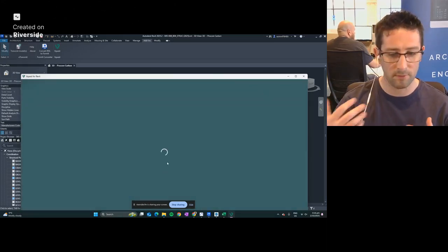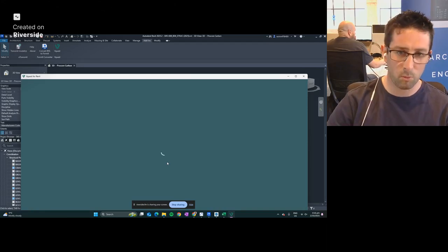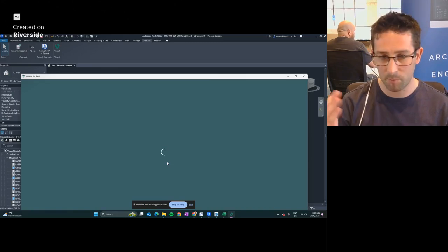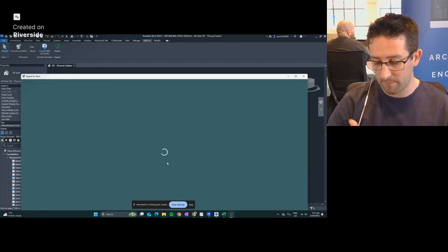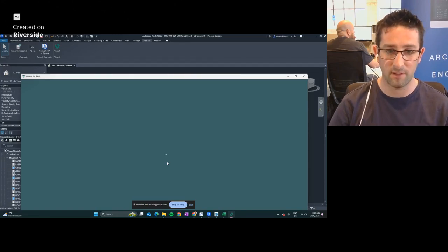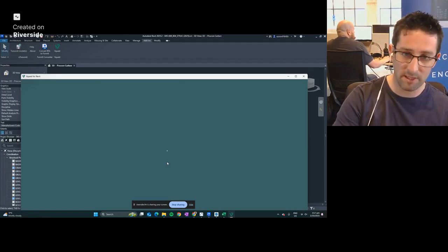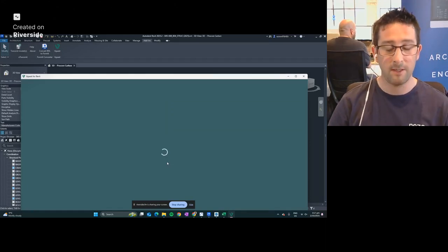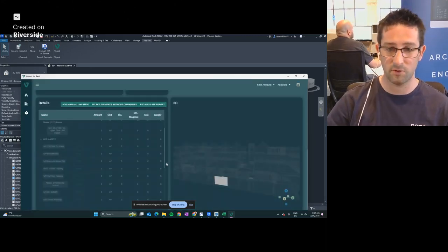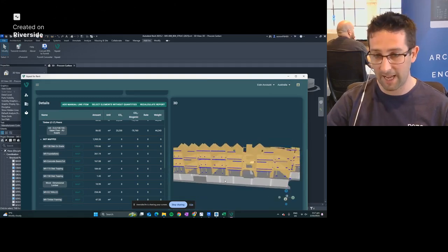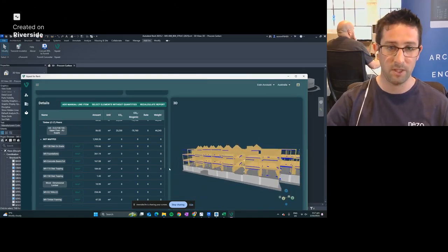So there's a variant for everything. If it's a wall system, you go to external walls, you choose the cladding system you want, say it's a brick cladding, and from there there'll be options for steel frame, timber frame, what spacings those studs are going to be at, what R value the insulation is. So we have 2,800 EPDs from neighbors, and then we actually have brought them together into assemblies that you can use to speed up your workflow. And there's about 6,000 of those in the library at the moment. And you actually can create your own assemblies as well for any variant that we haven't already thought of.